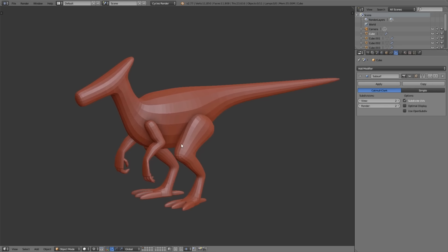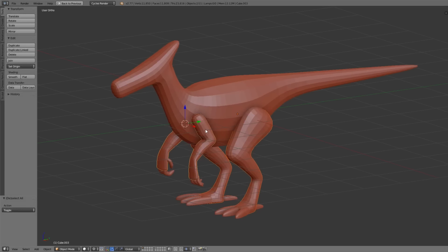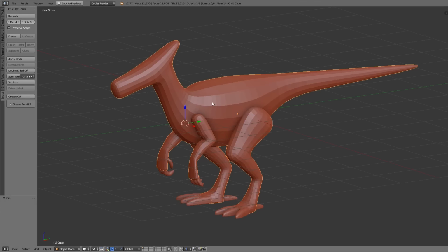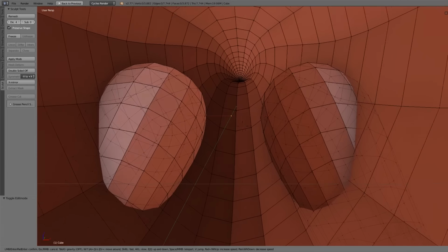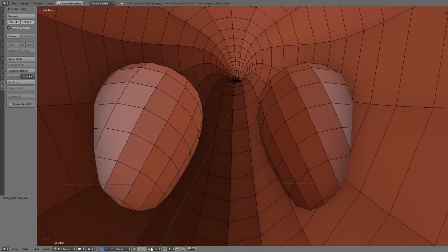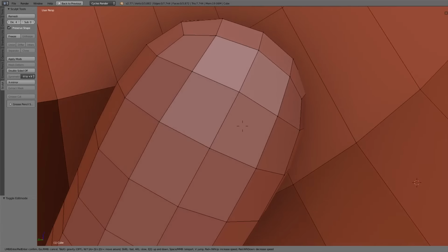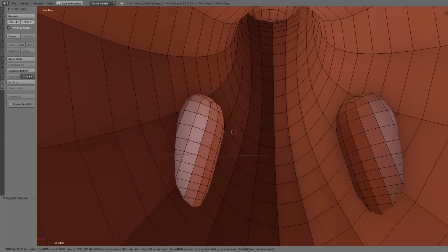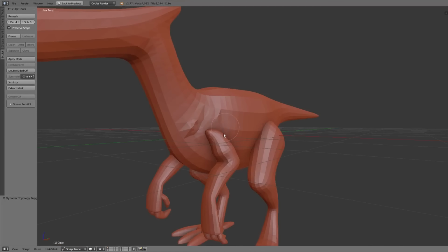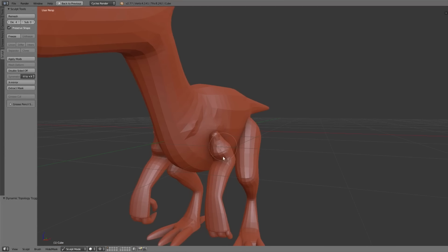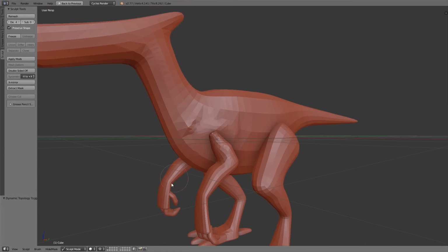For the sculpting, certainly we don't want to leave the arms and the legs separate, because we want to merge everything. So what not really would work is if I join all the parts using Ctrl J, because so the objects are just merged into one mesh, but the different parts are still separate, available in the edit mode. It looks like that the parts are sticked together. So the geometry is not really connected to each other,